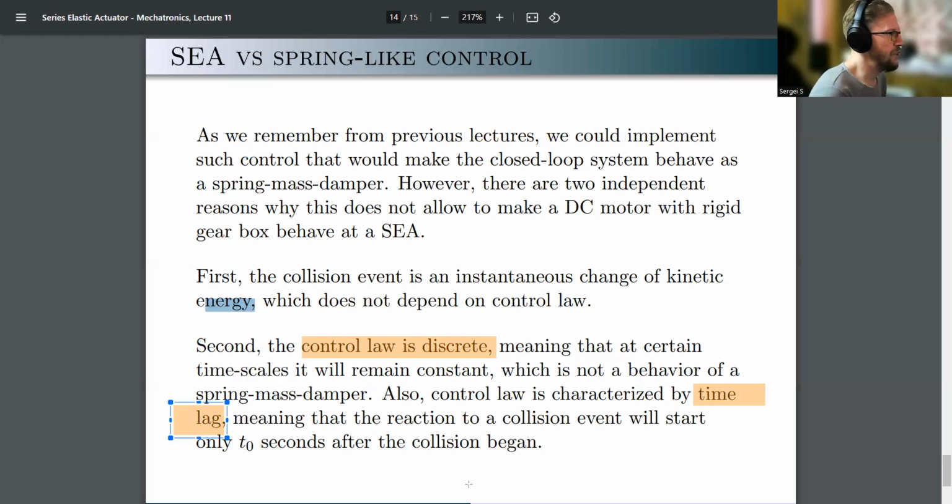And then maybe you could even do this whole thing without worrying about series elastic actuator. Maybe you don't have to insulate your gearbox and everything else if your collision event is slow enough, right? But practice tells us that the solution is somewhere in between. You don't have to always use series elastic actuators. They're useful. You just don't have to use them all the time.